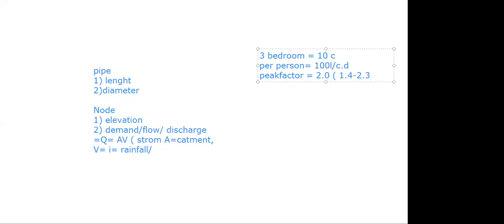In other words, 230% or 200%. You should increase whatever value you have by 30% to 200%. So there are some texts that will tell you something like that. So now we say therefore the water demanded for 10 persons for each house is 10 times 100 times, let's use 2. The range is 1.3 to 2.3. Let's use 2 so that it will be easy for us to calculate. And the value is about 2,000 liters per day, no more.